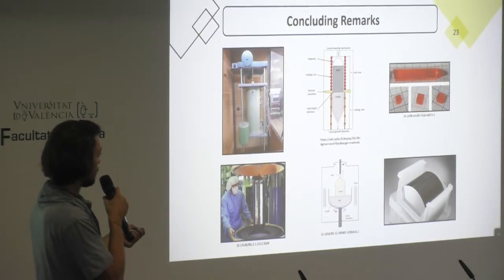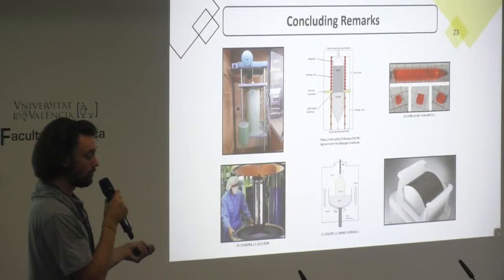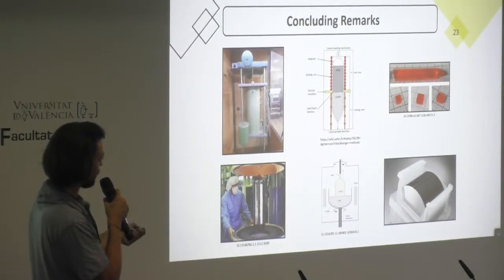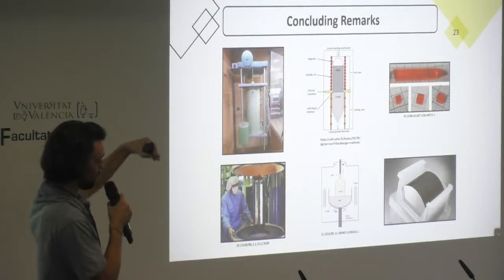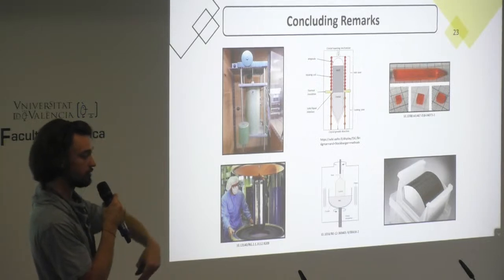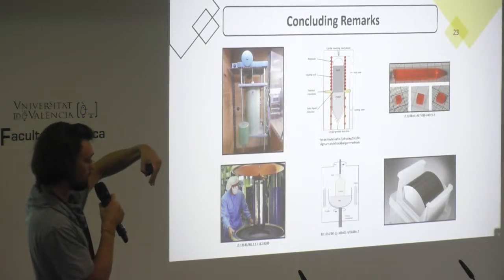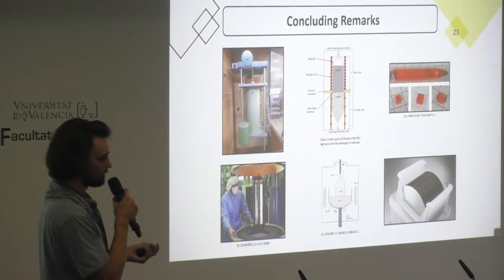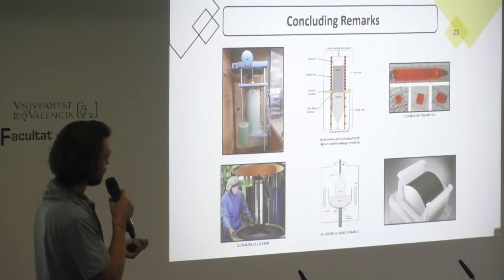a furnace in which we put our material in an ampoule, we melt it, and we make a temperature gradient with different heat sources, and we make it go through these gradients, so it begins being liquid and it ends up being solid. And if we do it well, we can get a monocrystal, which has these nice properties.